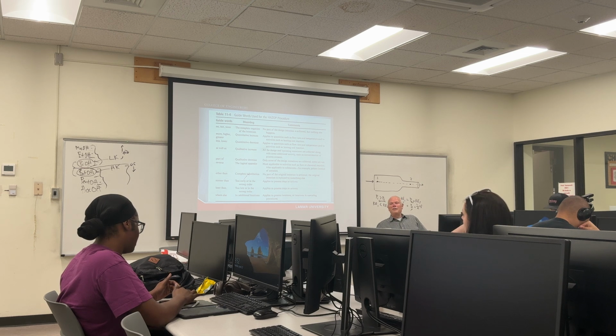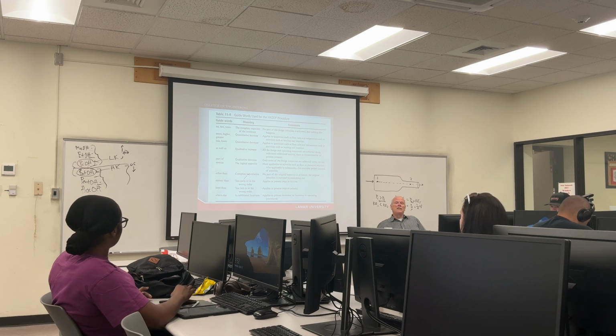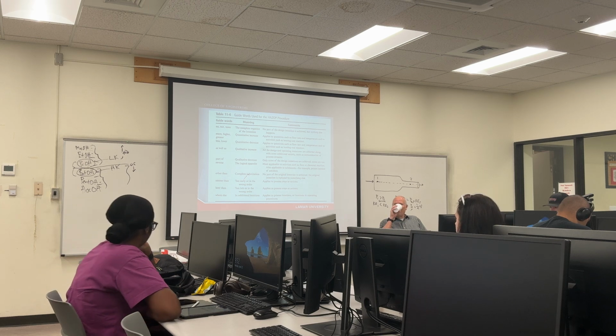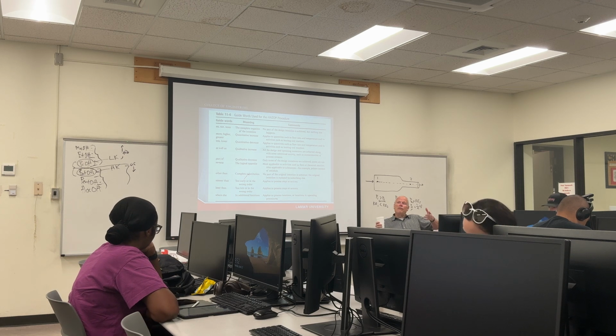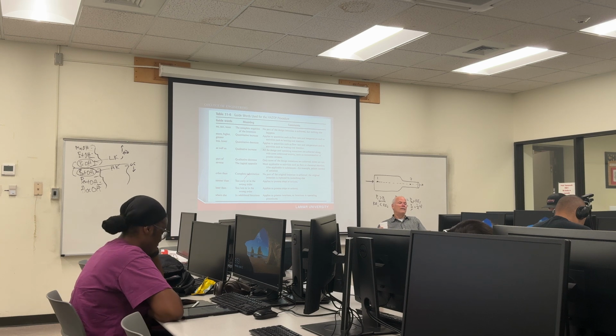What does no, not, or none mean for a reboiler? What's the design intent of a reboiler? Put heat into the column. Provide heat, right, to vaporize the bottoms. So what's the complete negation of that intention? Not heating up the bottoms. It doesn't work. Yeah, it's not vaporizing anything, it just stops doing that. That's your scenario, if you got a no, not, or none for your reboiler. Pretty simple, right? Got a column, got a reboiler, the reboiler stops working. That's the guide word no, none, right?